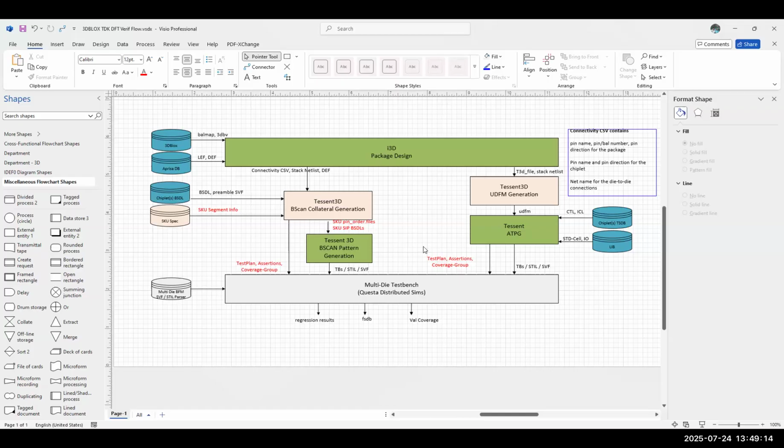Just to make sure, Bala, you mentioned something about RC delays and things like that. Is that part of the file? As Tony mentioned, the DFT tools will be looking for possible aggressors, victims, and shorts and things like that, and just purely the information is XY pins and connectivity. Okay. Actually, I misspoke. Not the RC, the bridging, identifying the bridging fault based on the placement information of the neighboring IOs, right?